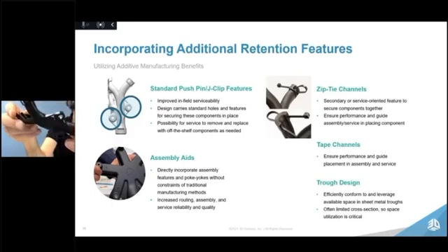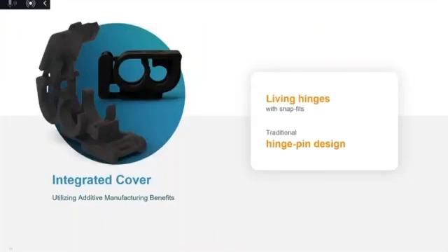And as an example of, again, the benefits of additive manufacturing, the assembly aids can be individual parts in themselves. The part that you see in the lower left picture on the slide there is a drilling guide that carries many features designed to perfect a step in the process of a fitment of a component in a transportation application. Things such as separate vacuum channels for placement, holding and debris removal, drilling guides with sequencing, standoffs for maintenance of vacuum placement are just a few things that can be incorporated. Next slide, please.